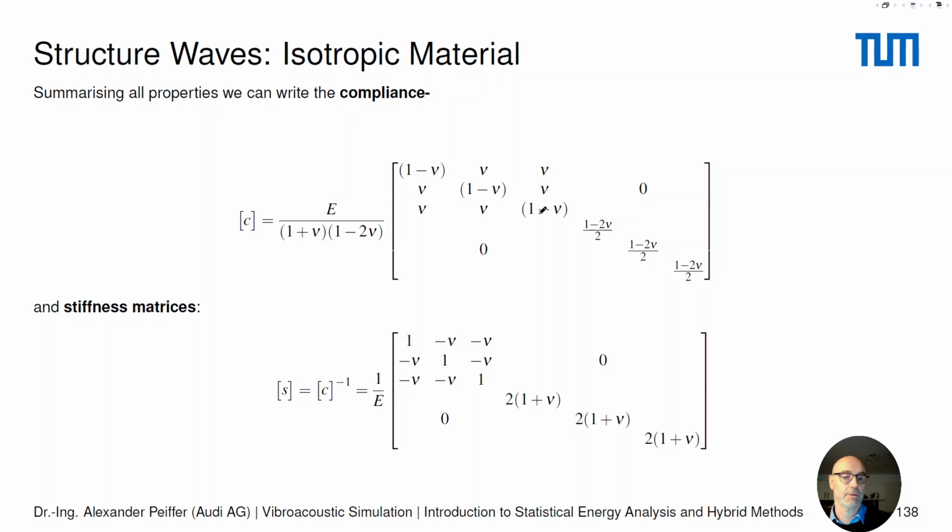So we have the same here on the diagonal. These are the same. So we're ending up, logically, because we have three constants, with exactly 3 coefficients in the compliance matrix. And in the stiffness matrix, that's the same. We also have 3 constants. Please note that many of the other constants in this matrix are 0, simplifying things a lot.